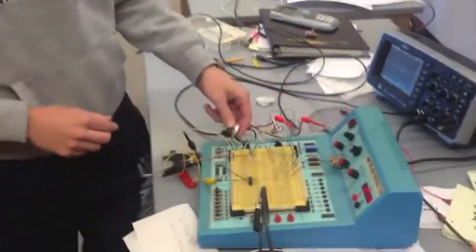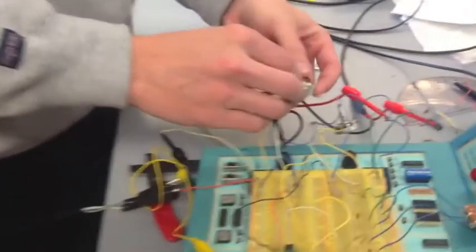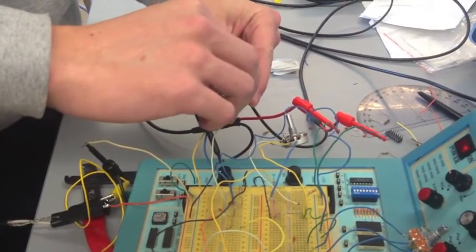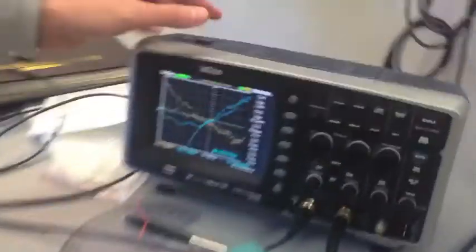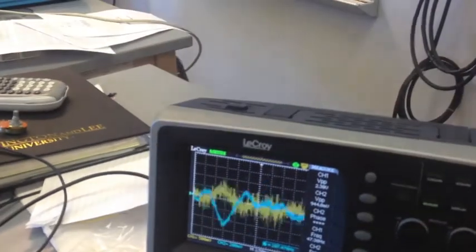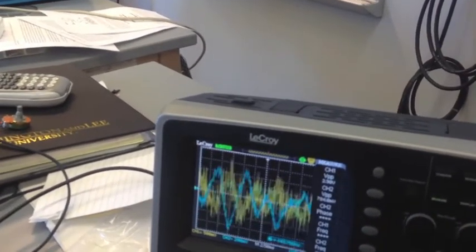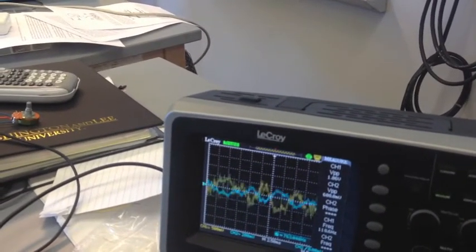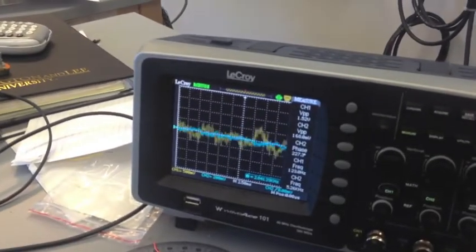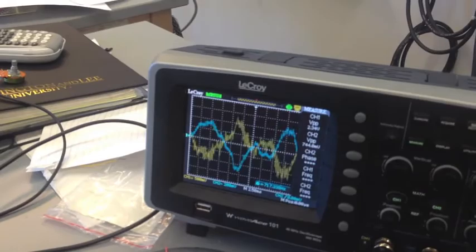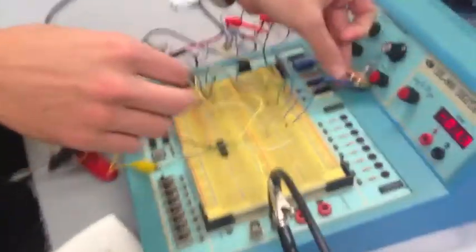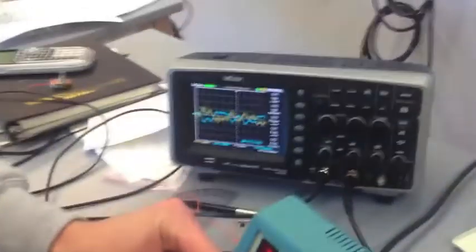We also have separate bass and treble controls. This is the bass control. Go ahead and crank it up. You can see the bass frequencies, the longer waves are jumped up now, and as I decrease, the blue is the output. The blue wave is going to be decreased for the longer frequencies, or longer wavelengths. Sorry, lower frequencies.